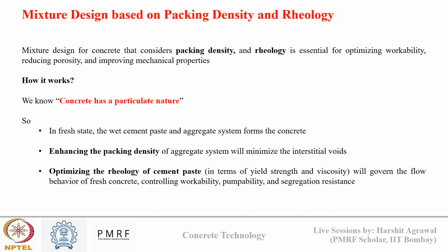So, till now, we have discussed all conventional forms of mixture design, which were based on one common aspect, strength and workability, defined as a function of W by C ratio. Now, we'll look at an advanced form of mixture design that is based on packing density and rheology. A mixture design of concrete that considers packing density and rheology is essentially for optimizing workability, reducing porosity, and improving mechanical properties.